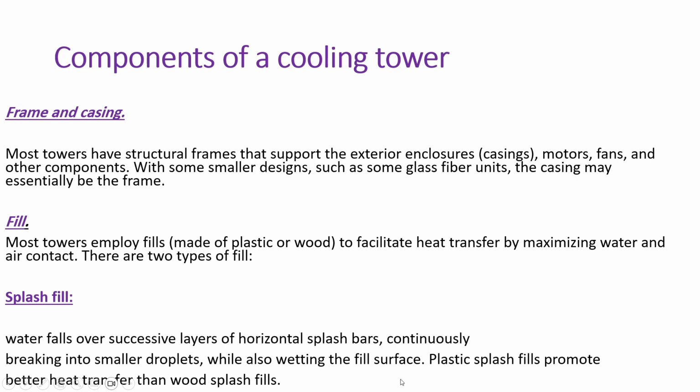Splash fill is horizontal, but film fill is vertical. Plastic splash fills promote better heat transfer than wood splash fills. So when we're talking about heat transfer, plastic splash fill is better than wood.